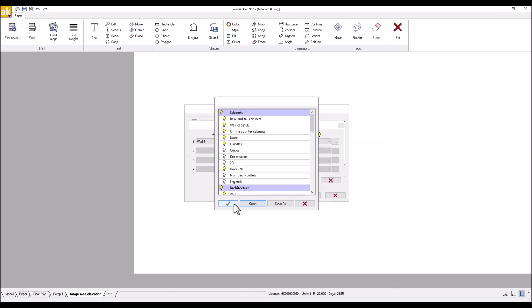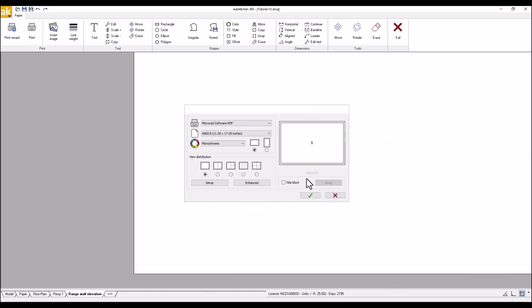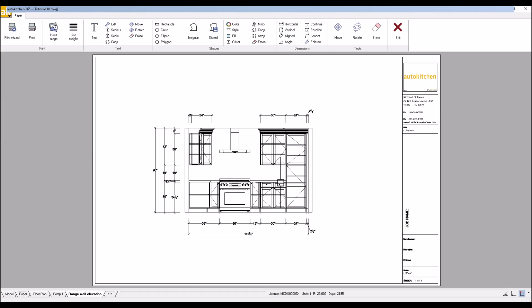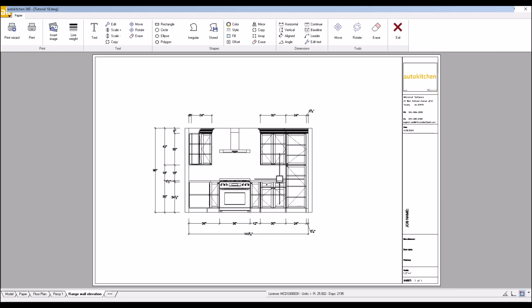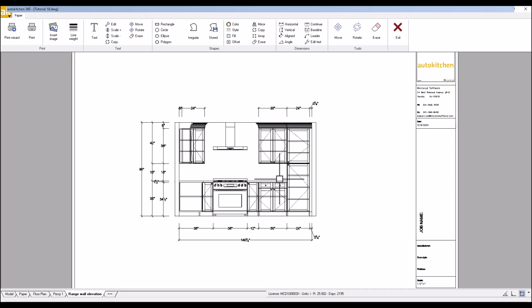6. The selection for title block should be the same, Model 10. Then, click the green check mark buttons to confirm until you see the view to be printed on the screen. Remember, the elevation will be in wireframe, but this is not how it will print. Also, if the view is not centered, you can manually center it by double-clicking and then pressing and holding the mouse wheel and panning until the view looks centered. Once centered, double-click in the gray area. When finished, you can click the Print button.